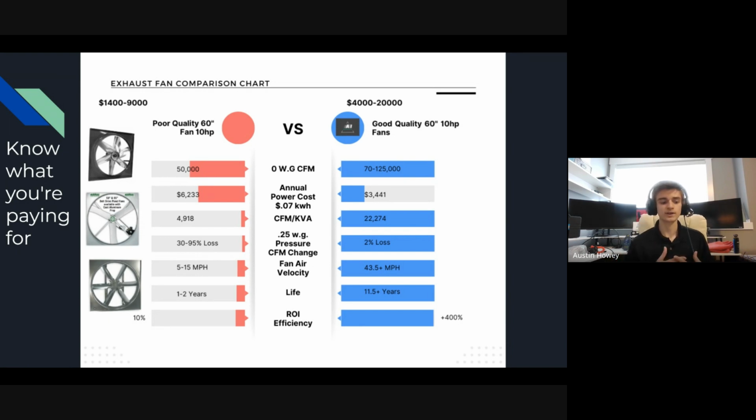So your fan essentially loses output, it loses the velocity that it's going through, and it's also overamping your motor. This is another common problem: if your fan and motor are under a lot of static resistance, it's stressing out your motor, especially if you're using direct drive, because with direct drive you're putting all the torque straight into the motor. There are no belts or anything absorbing that vibration and that torque.